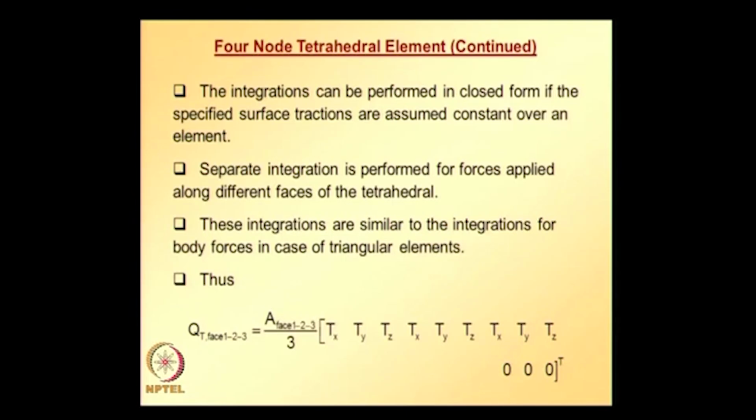And again this equivalent nodal load vector is based on the condition that Tx, Ty, Tz are constant. If they are not constant, then we need to do numerical integration of the previous equation, assuming Tx, Ty, Tz as functions of spatial coordinates.